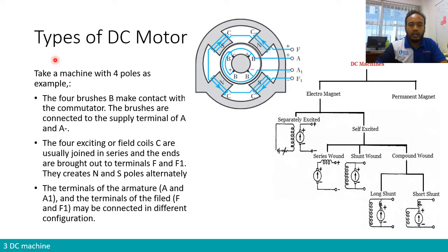So as we have discussed in week 1, we know that the main principal components of a DC machine are divided into two: the stator and the rotor. The stator basically produces what we call a magnetic field inside a certain area, where you have later an armature which will be fed with a current as well to produce its own magnetic field. So the interaction between the magnetic field of the armature or the rotor with the field by the stator will create basically the torque, right?